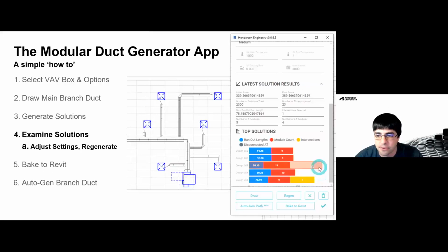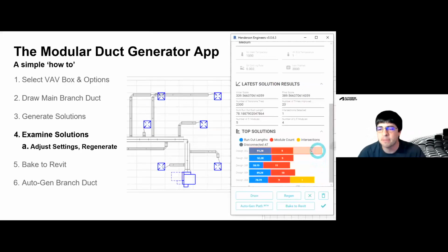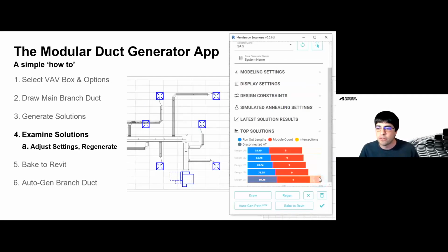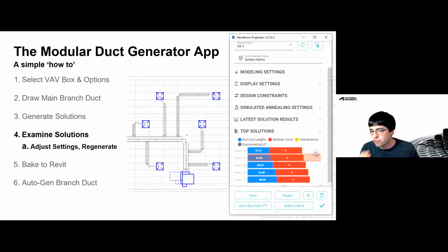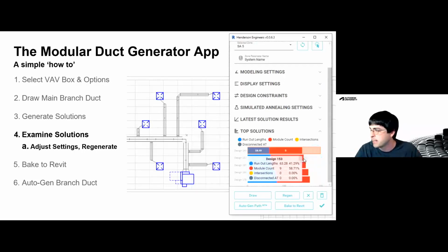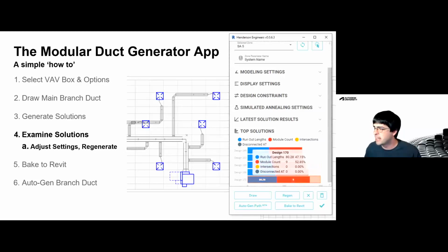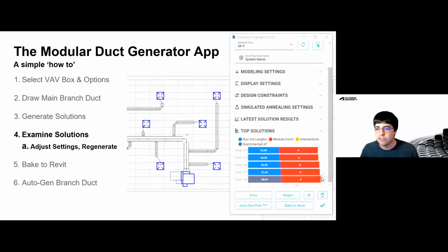So once you have some solutions, you can examine them. In that little bar graph thing, you can click between them to activate different ones. If you hover over them, it'll give you a little more detail about each one and what those numbers and bars represent. So you can adjust some of those design constraints we looked at earlier in settings and regenerate until you have solutions you really like.